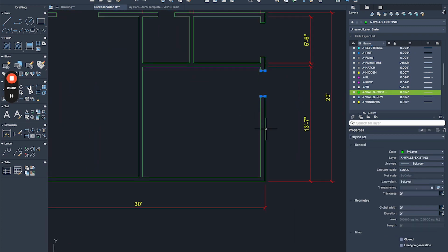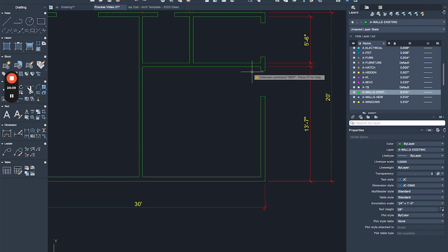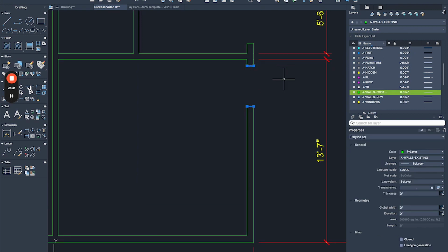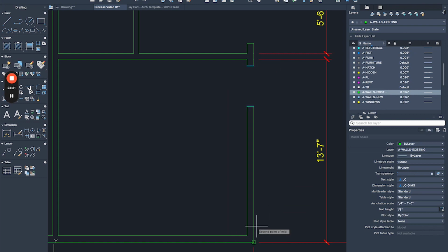And then I'm gonna mirror this from here to the opposite. So I can do the shift command that I showed you earlier. We're gonna do mirror, MI, okay, that's mirror. I'm gonna hold the shift button on the keyboard, then right click, and I will get this temporary snapping setting. I'm gonna click that I want from the middle of here to here, and this allows me to do this. I don't want to erase the source, and then we have these and we can trim. Now I'm gonna undo and go back.